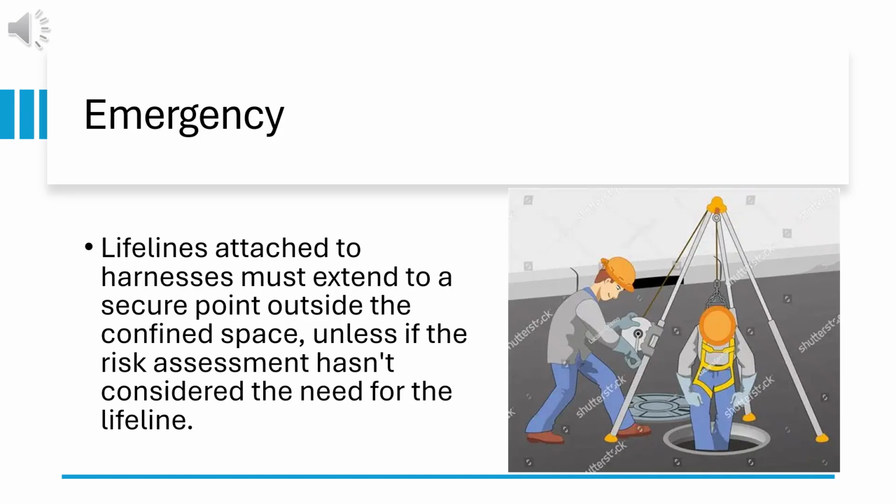During any confined space operation, the rescue plan must be prepared before work begins and must be clearly communicated to all personnel involved. This includes entrants, attendants, supervisors, rescue teams, and control room staff. Everyone must understand how an emergency will be detected, how evacuation will be initiated, and how communication will be maintained throughout the incident. A key component of rescue readiness is the use of proper retrieval equipment.